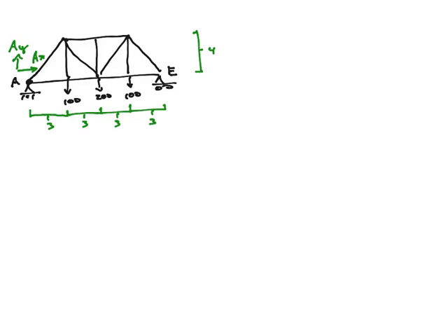So you know it's negative, that means I thought it was up, it's actually down, or vice versa. So you just change the direction and make it positive again. The magnitude of the reaction, you'll still get the right answer. It's just a matter of whether the direction is correct or not.